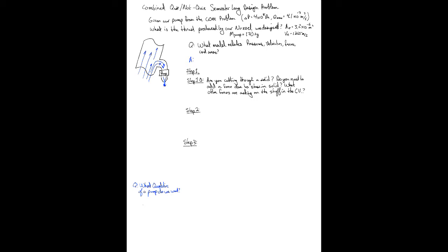So we've already learned quite a bit about how to design this tower. We know that we cannot put a very large pump down at the bottom of our tower and expect to just push the water up with enough pressure to produce the thrust we need. That requires very thick walls, which are very heavy, which requires more lift. Then it's just a runaway problem, right? So the reality is that we want very thin walls here with occasional booster pumps that keep the pressure quite low inside of this main tube that is going up.